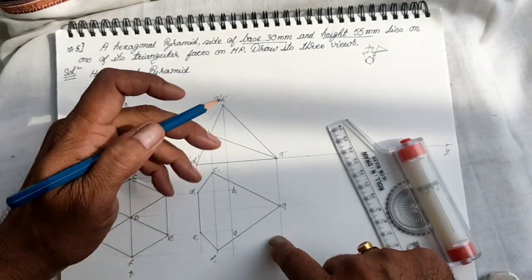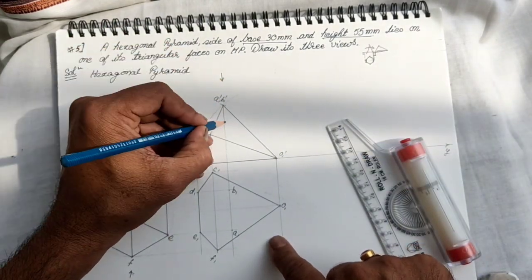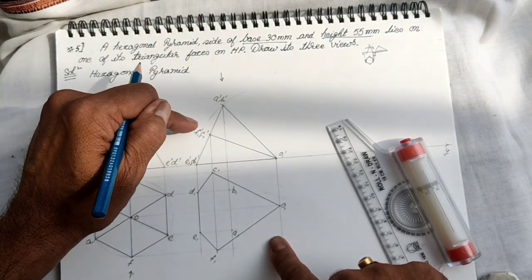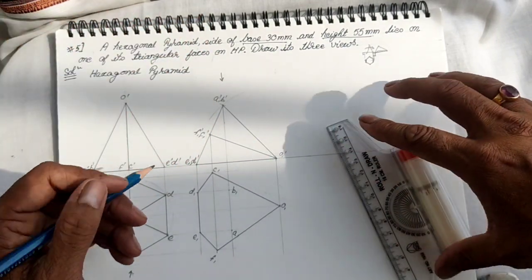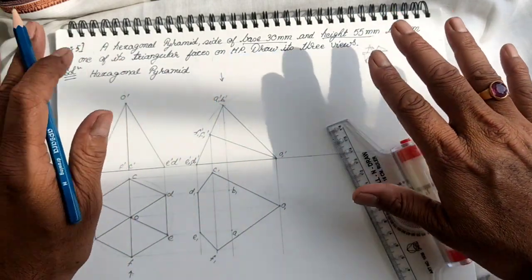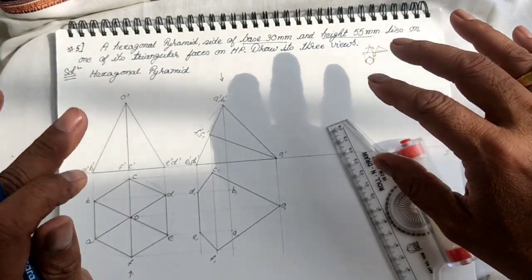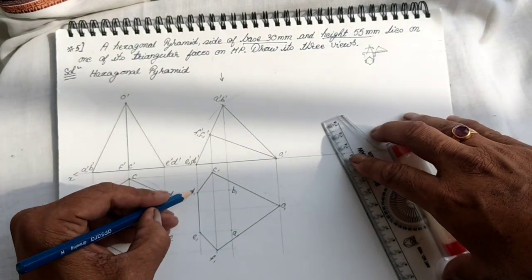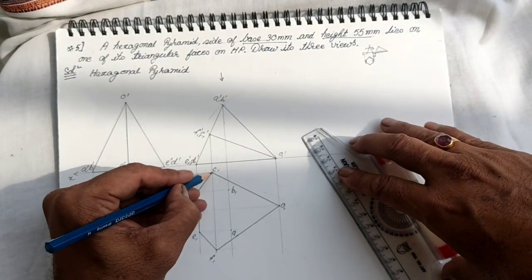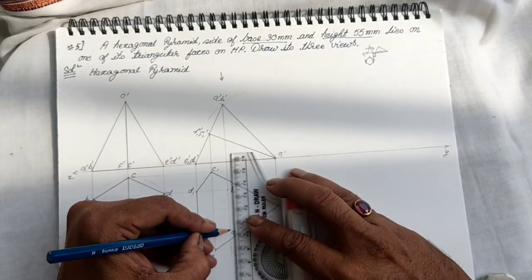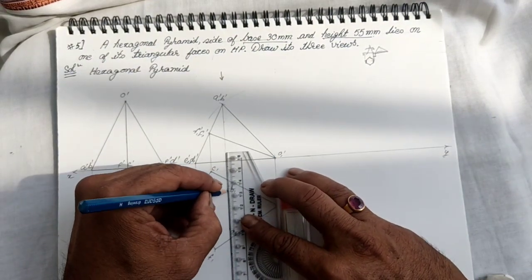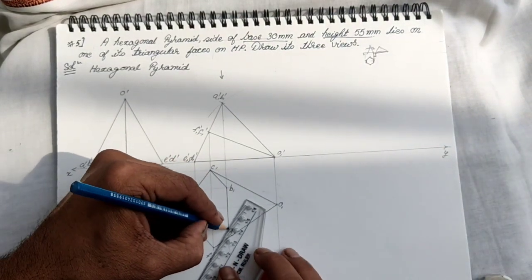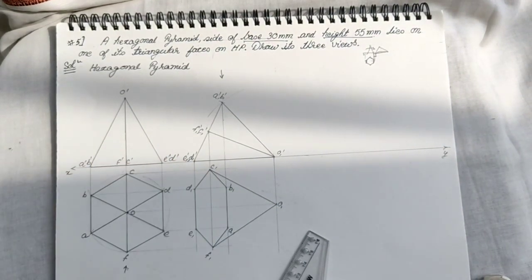So this is a top view. That means we are looking at this solid from the top. So base is exposed. That means all the base edges are visible. So all base edges will be solid. So AB, BC, CD, DE and EF. Out of which CD, DE and EF are done in the first step, the remaining are AB, BC and AF.